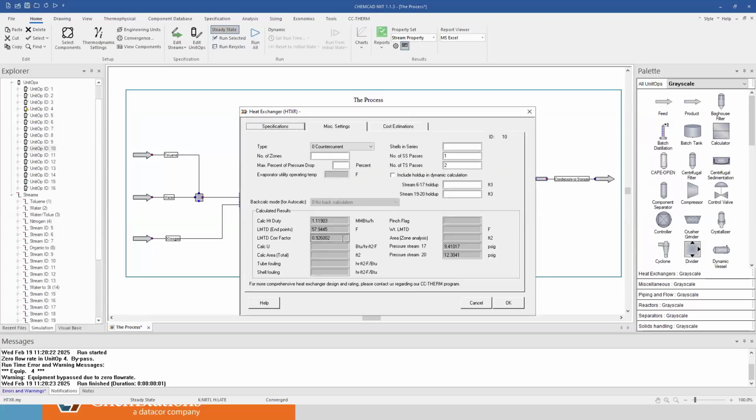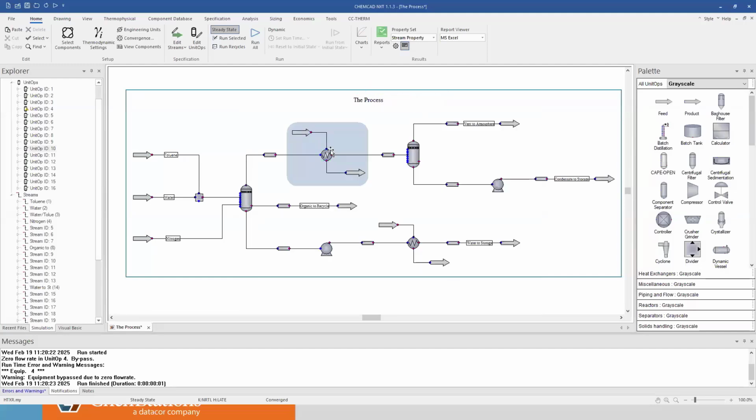You see, now I have sort of a correction factor. So that looks a little bit more decent to me. There is a correction factor, so I have a calculated heat duty that is a little bit more. So I can go with this and now go into CC-Therm. Okay, so I can say that looks all right. I have this, I can go with CC-Therm. So I now have an initial estimate, and I'm going to go into CC-Therm and start modeling and sizing my heat exchanger.